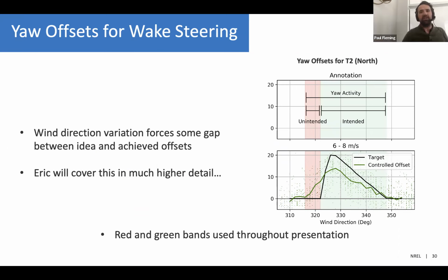But in point of fact, wake steering seems a little bit more suitable to offshore sites for a few reasons. One, the offshore conditions are less turbulent, meaning wake losses are expected to be more intense. And also there's a lot of stakeholder consideration that drives offshore sites to be fairly gridded, meaning you get long lines of turbines in a row producing wake patterns, whereas onshore you have more freedom to design irregular farms that can minimize wake effects just by spacing turbines out or putting turbines on ridges, things that aren't necessarily available offshore.